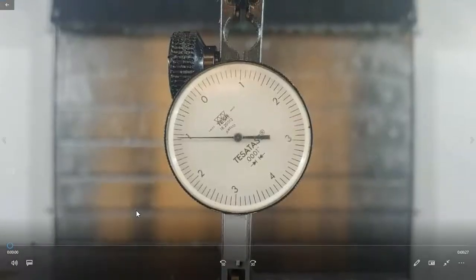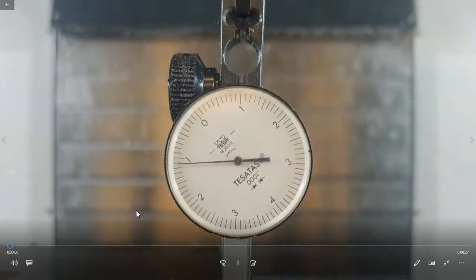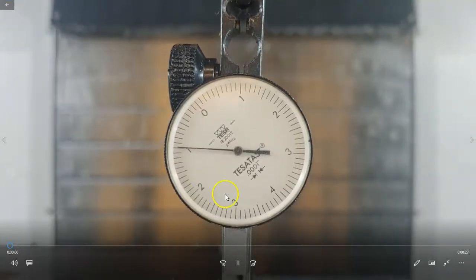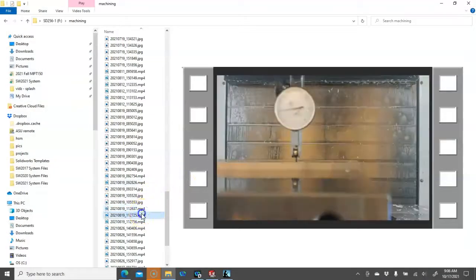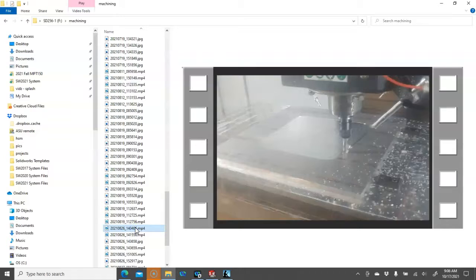So bring that down until it touches. And then, I think that's the vise, so I think I'm one ahead of myself. Yeah, that's the vise that we're trimming up. All right, so if I run the indicator across the 60 inches back and forth through a sampling, I will get around 2 to 5/10ths of a thousandth on the surface.